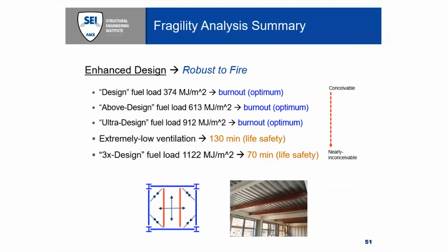This provides a truly reliable backstop for a design which meets the minimum mandatory performance objectives of ASCE 7. But for more expected or conceivable conditions, it's providing optimal performance. There's no collapse under full fire burnout. So overall, the variety of conditions in which the structure performs adequately compared to the nominal case demonstrates the reliability and robustness of our enhanced design, which was not possible with the nominal case.